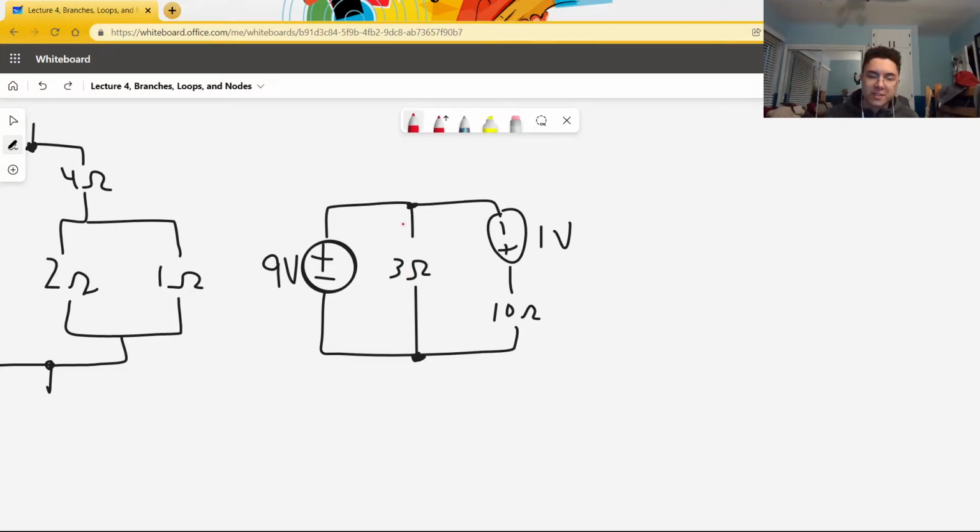So, two useful things to know. First of all, in this branch, the current is constant the entire way through. Secondly, all of the voltage gained by an electron in this branch needs to be used up in this branch so that the electron can go back to the beginning of the battery. So if an electron gains 9 volts traveling up across this battery, then it will lose 9 volts traveling down across this resistor.